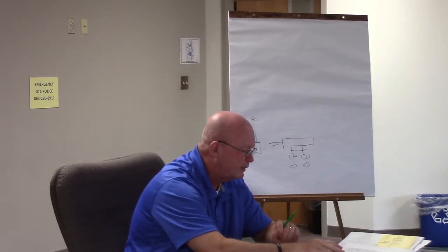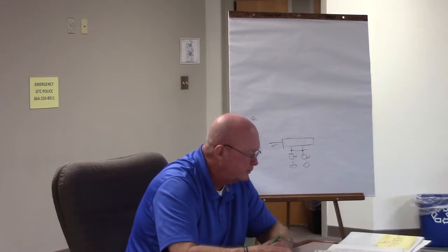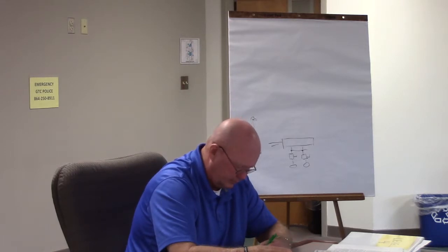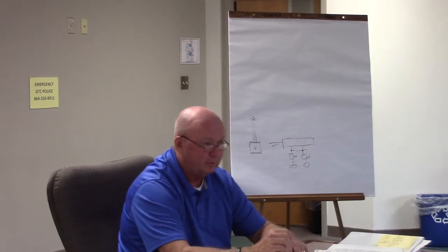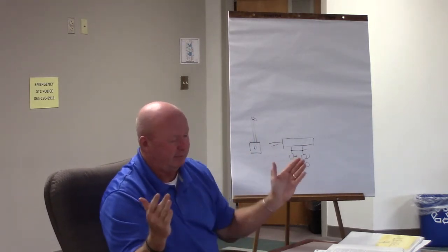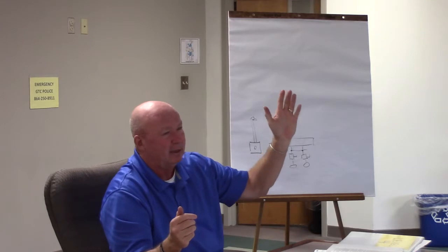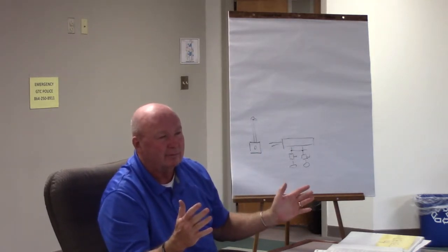Use of the 100-foot tap rule is limited to installations in a high bay manufacturing building with a wall height of over 35 feet. Yeah, and that makes sense, that 100-foot rule, 35 foot. Regardless of what you do, if you've got 100 foot, you have to go up 35, go over, and go down 35. That's already 70 foot.